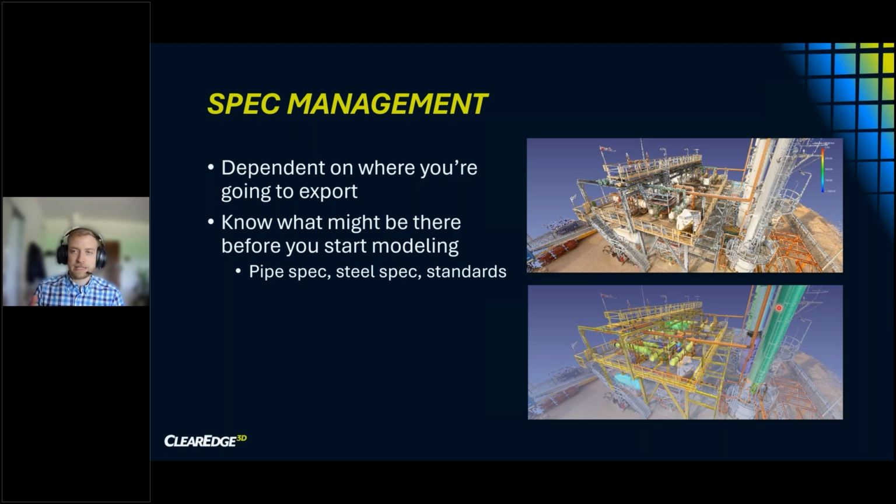And the value that actually gets sent to Revit and is used by Revit is going to be the nominal diameter, and we'll see this in the piping standard when we go into that workflow. But it's really just the nominal value, and so that's the only thing you really need to do if you want to define initial custom specs: your actual diameter and your nominal diameters. And that's the value that gets sent out and really evaluated by the final deliverable software. That's the one to keep in mind. There's other information for valves and flanges that we'll briefly poke at, but that's the high level, and it is a spreadsheet that you can manipulate.